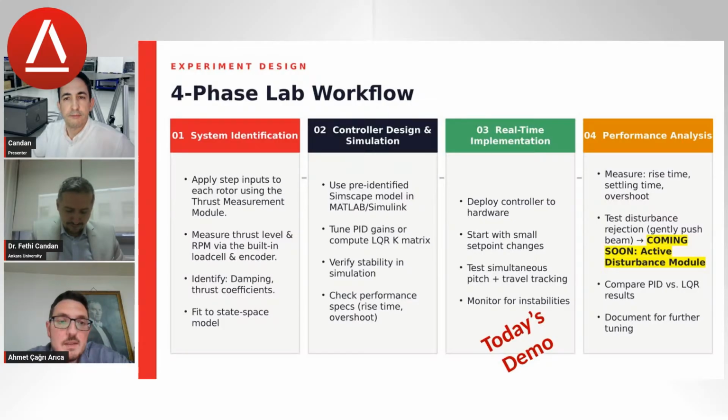Tune control parameters, verify stability in simulation, and check performance, for example transient response: maximum overshoot, rise time, and settling time. You can change these transient response characteristics of the system by changing the control parameters.